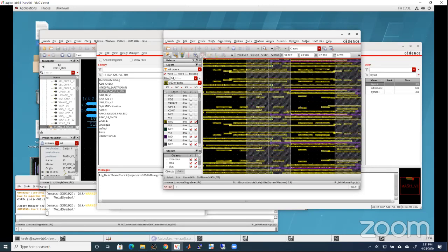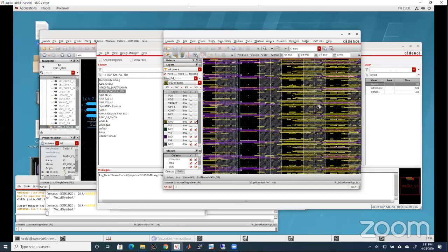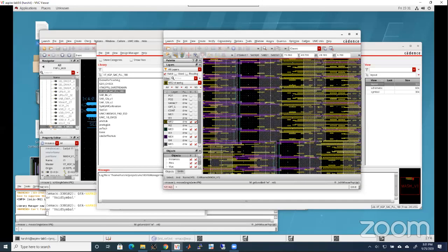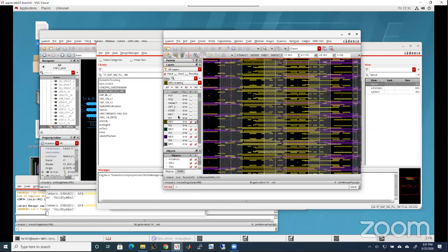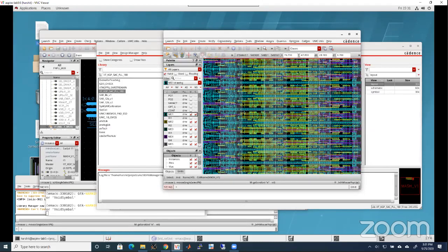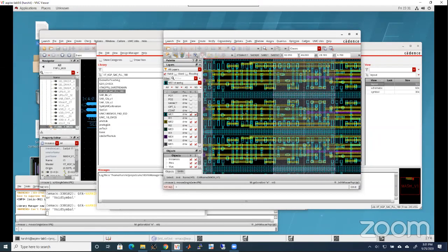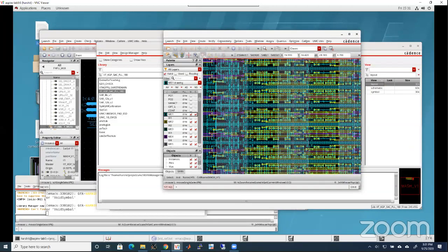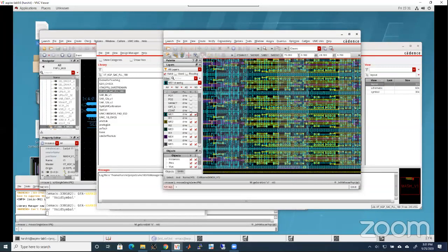Because standard cells don't use metal 2 and 3, all the interconnections are done using them, and you see that these are the tracks between the VDD lines. And if you see, the power lines are here. Between the power lines, the routings have been done. These power and ground lines are over here: ground, power, alternate power and ground lines.